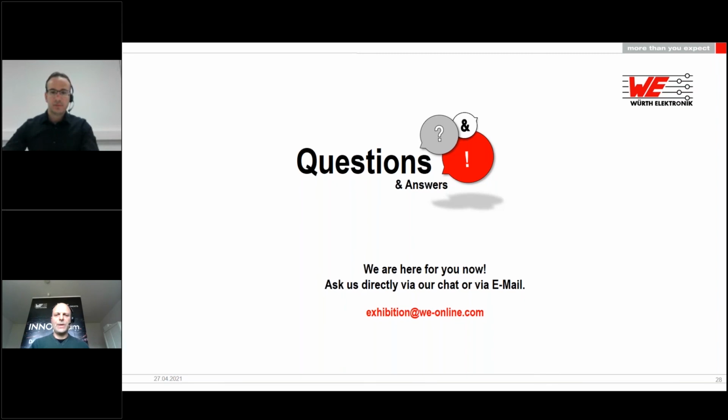Okay, can you hear me? Okay, I would like to answer that question. I think it's a good one. I would say indirectly, yes, a higher rated isolation also helps with CMTI. And why I say that is because when we talk about higher rated isolation, it means that we have actually more isolation, more separation between the primary and secondary windings. Therefore, the distances being bigger between the primary and secondary, the capacitance is lower. Therefore, this will help with CMTI. I hope this helped answer the question.